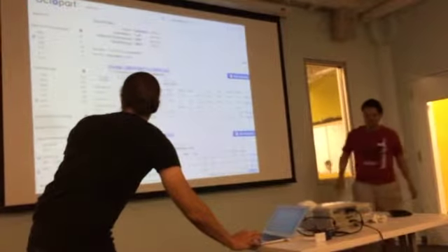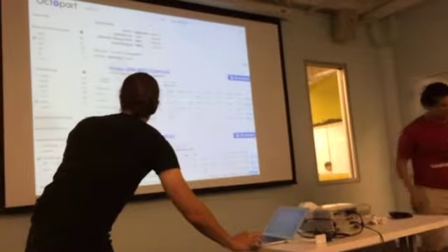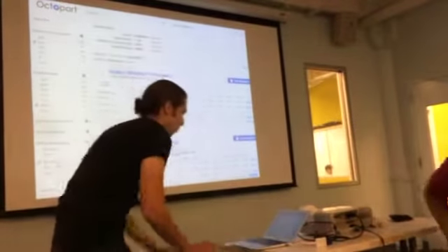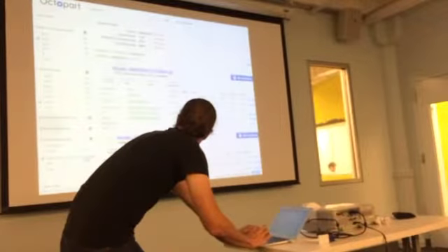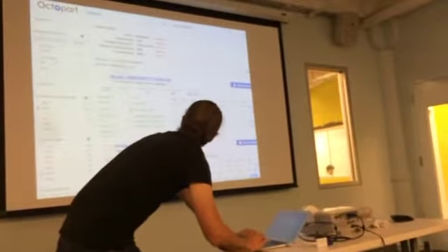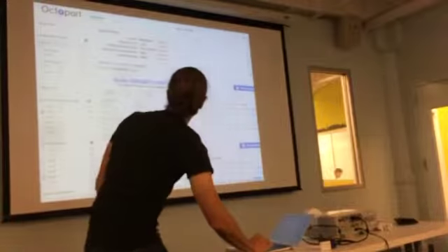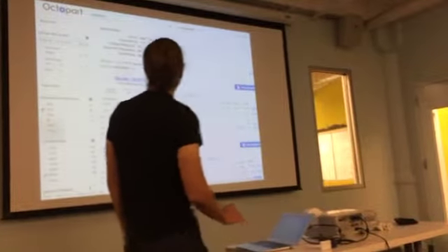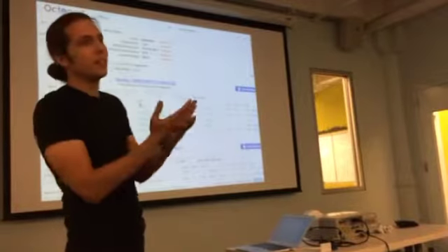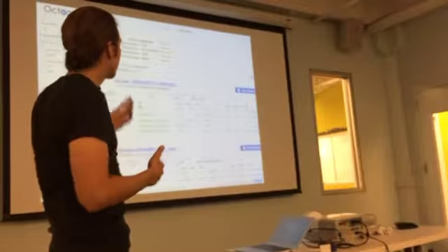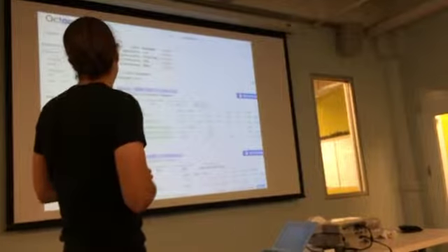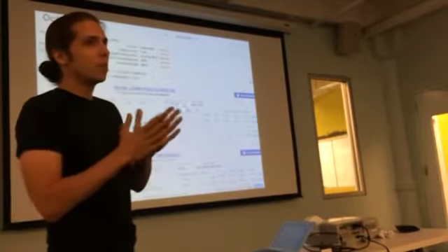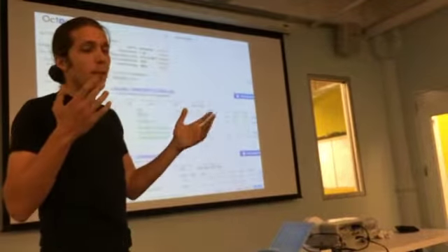Yeah, so there's a slider here. Anyway, we can just set the minimum voltage right here. So let's do 15 volts, at least 15 volts. And now we're down to 48 capacitors. And so this is pretty good. I think all these capacitors will pretty much do the job here. So we went from 1 million capacitors down to 48, and there are some more things we could filter on, like tolerance and a couple other things, but this is pretty good. So this is how you would do a parametric search on Octopart.